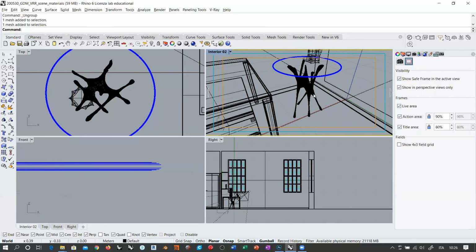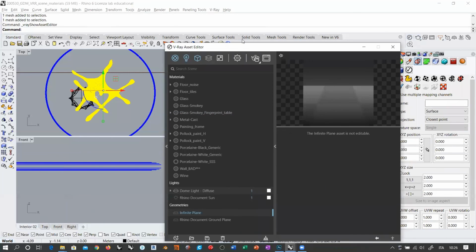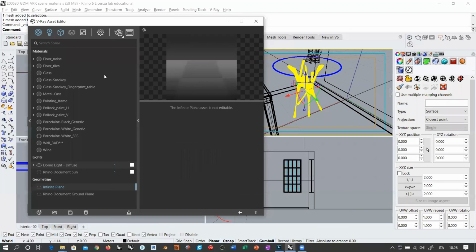The other option that you have is going into materials, and I don't know if you already looked at this by yourself, but there is a relatively new texturing available in V-Ray, which is called Triplanar. Now, I'm not going to use it because actually Triplanar, in my opinion, works perfectly if you don't have a closer look at the details of an object.